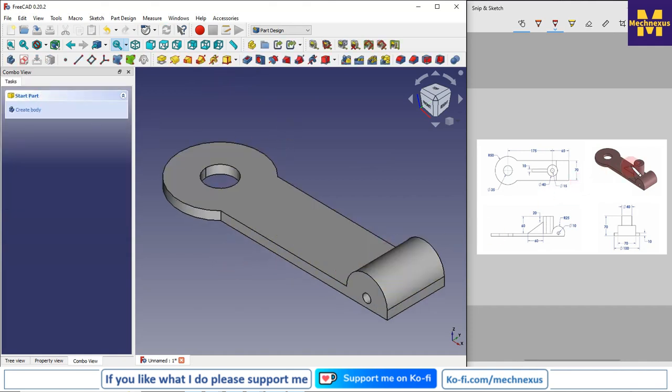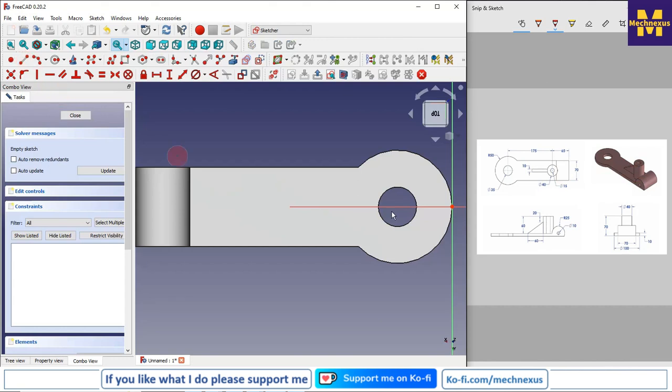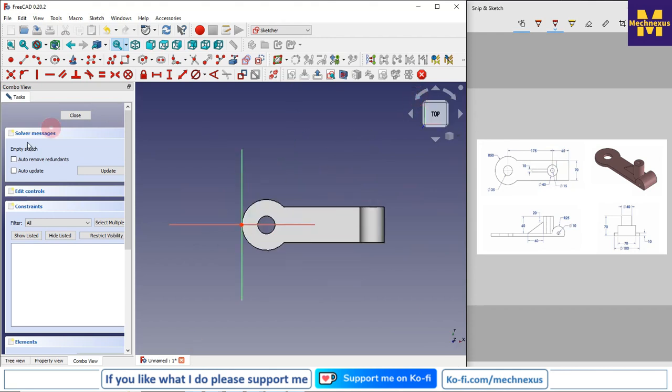And now we will make one cylindrical, we will make a circular boss here. So for this I will select this face and I will say create a sketch. So the position is 65, so I will rotate my model as per the drawing view.